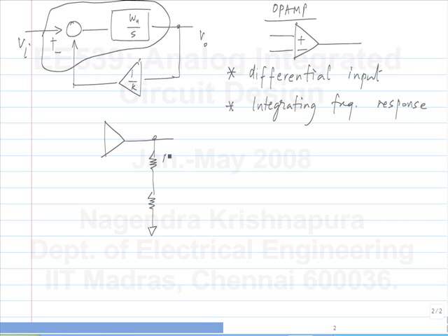We have a voltage divider that can implement the feedback path, and we have to take the difference between the input and the feedback quantity, and the integration happens inside the op-amp. Okay. Of course, the op-amp behaves like an imperfect integrator, that is, it has a finite DC gain and also some parasitic poles and zeros. Okay.